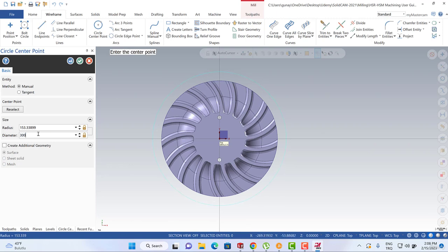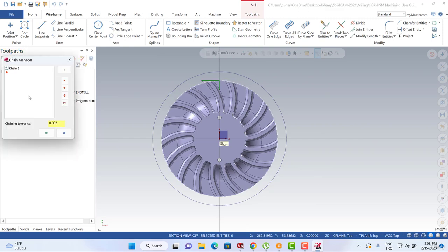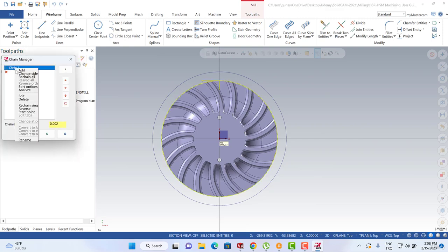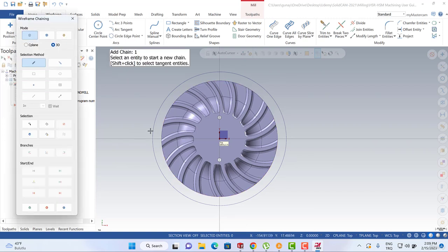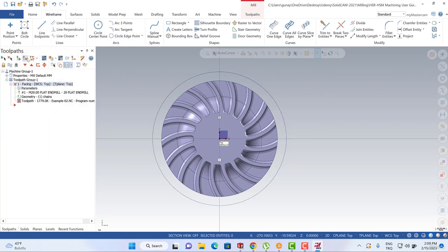For example, it can be 300, and then I can hit the geometry button, and then we can use the right mouse button and delete this one and add new one. When we add new one, actually we can also use the reverse direction options here, but it's not important. And then we're gonna calculate our toolpath according to that stock.